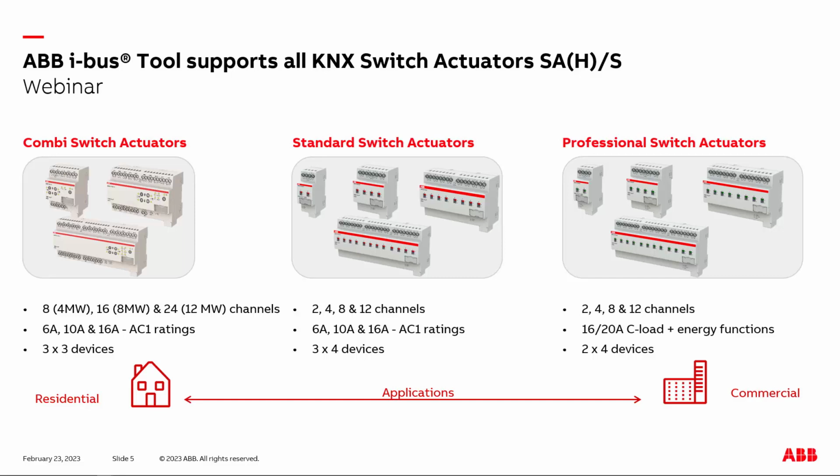These are different relays, but you see here a traditional version with manual operation via the lever of the relay in principle. So proven components. The professional ones are mainly different in terms of the capability of the relay, plus the optional so-called energy functions. This means we measure the current per channel, and out of the normally constant voltage we can calculate power and energy consumption. So we have some electrical values. It's an option, but available. And here we talk only about the high performance relays up to 20 ampere.